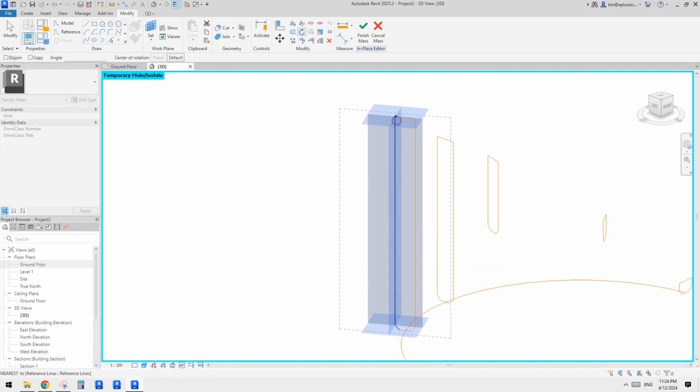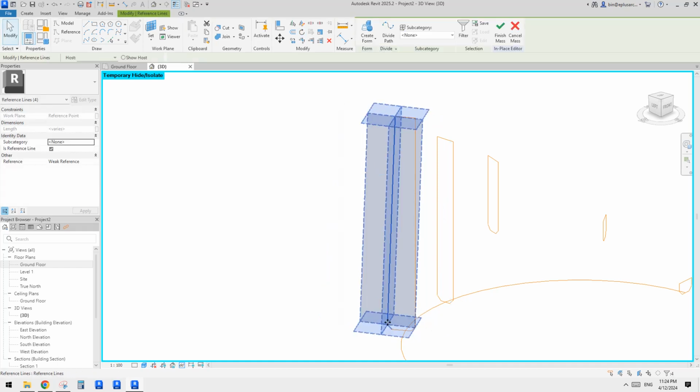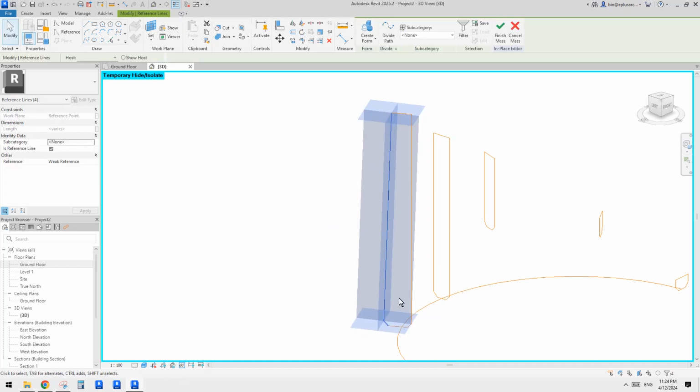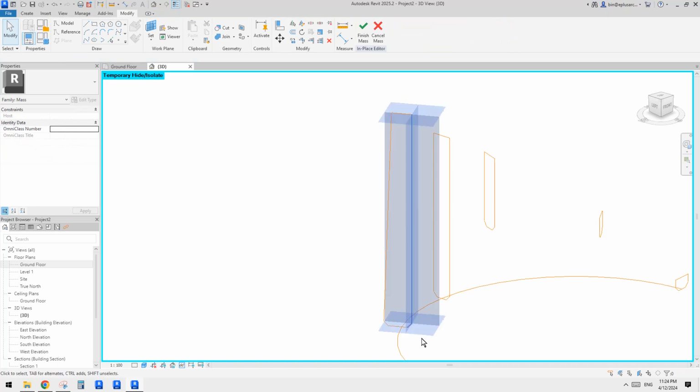Okay, and then I'll place the base point, the center of rotation, onto this point, and rotate this by maybe 2 degrees. So just make this bit, the base, a little bit wider. I'll do it to the other side. So RO space, click on this, and click anywhere actually, and go up by 2 degrees. Okay, so now you can see it's narrower on the top, it's wider on the bottom.